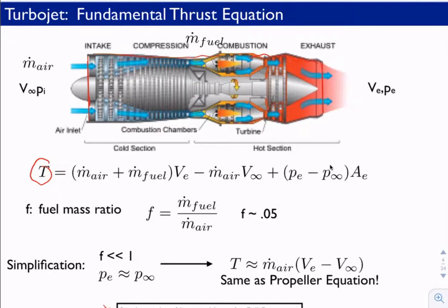So starting from the pressure force, you have the exit pressure times the exit area acting in this direction here. So that actually is a thrust force. So that's why P is on the positive side here. A drag force from pressure on this side, pushing backwards. That's P infinity, or free stream pressure. So you have this pressure difference acting across this control volume that actually can contribute to this x direction force, or thrust drag force. We also have a change of momentum.